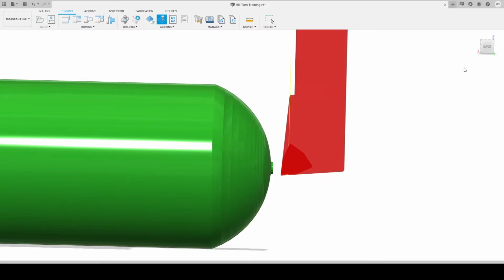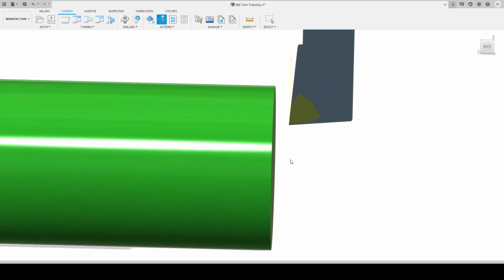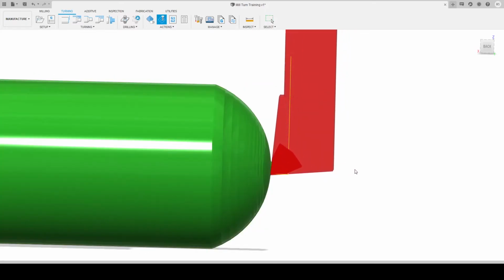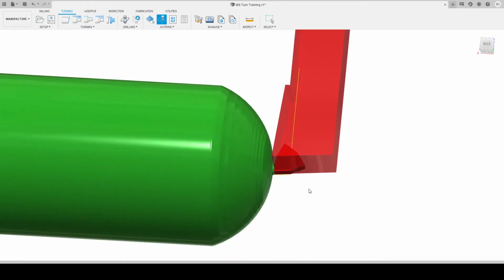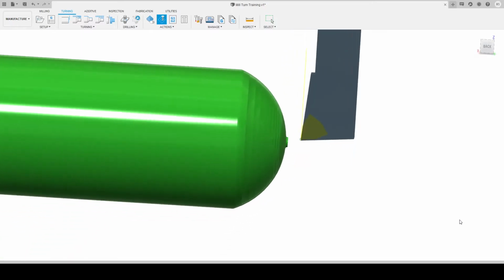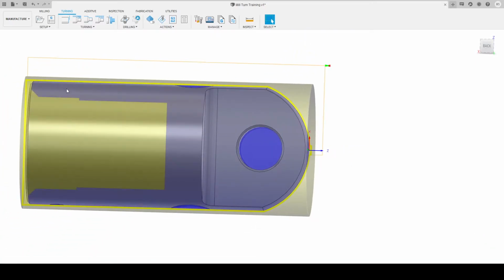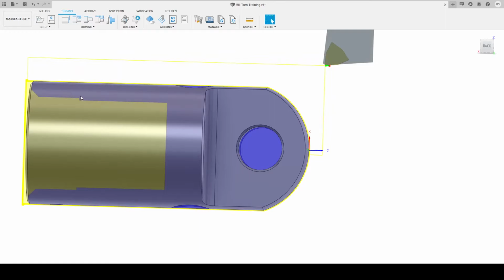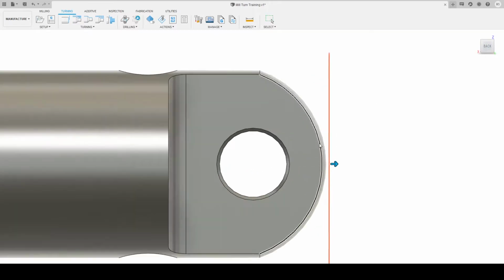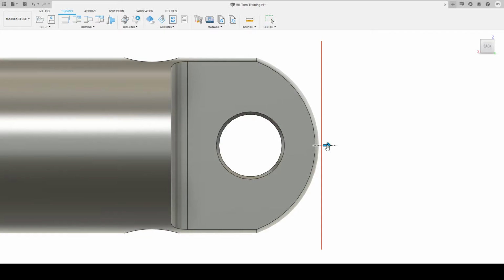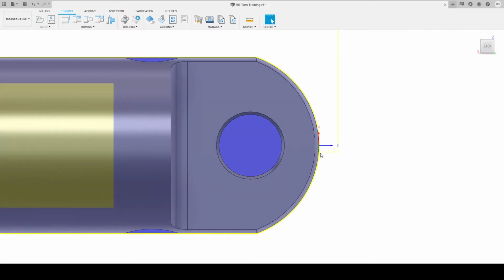If we click info on the second tab, you can actually see what move the toolpath is in. So we're rapiding here, and we're still rapiding until we actually get to the part. This move here is a rapid move, which is not ideal. So let's click close on that, and then our finishing toolpath, we'll edit that, and all we do is add a value to the front of the part. We know that we've left 1 millimeter stock, so if we go 1.5, we should be no worries.